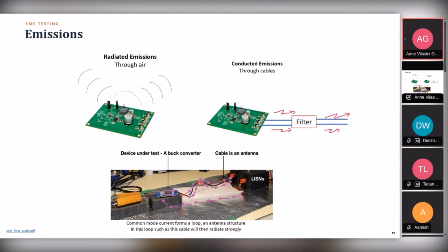So the noise is starting as a conducted problem, and the same cable then radiates this noise into the air. So how you can control it is you can control the current on the cables, and then you can also kill the radiation. Which is exactly why so much of the EMI design comes down to the filter and the common mode current.